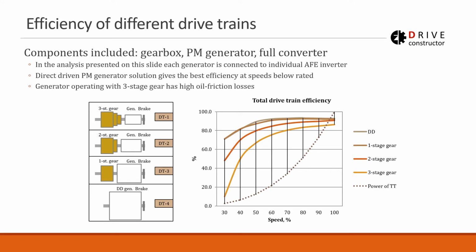We understand quite well efficiency of individual system components, like of an electrical machine. But what if the electrical machine is put together with a gearbox and then frequency converter and transformer to form the total system? So what is the efficiency of the total system? Well, the answer is efficiency of the system is the product of efficiencies of its components. It's easy. But what is special here?